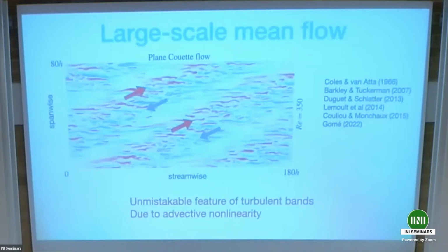Okay, so then this brings me to this. The issue, and again, this is why the planar flows are so different from pipe flow. Pipe flow is very constrained. I'll just tell you, because I took out the slide. It's simple. In pipe flow, I could write it on the board, but I would rather do it with my hands. Where you have the quasi-laminar regime, you have the parabolic profile, and where you have the turbulence, you have a turbulent profile. We know what those individually look like, and then you're transitioning between one and the other.